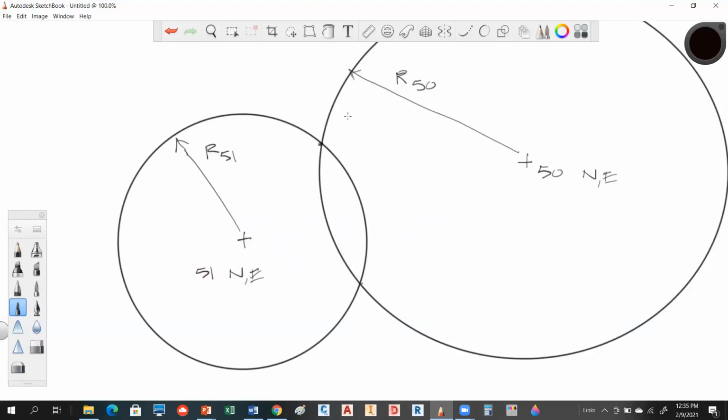So we know that distance, we know that distance. Where these two circles intersect gives you two solutions. Again, you could talk about either that point or P prime. So this is the type of intersection that will also yield two solutions, and this is referred to as distance-distance intersection. So all of these things are used, we use these all the time.